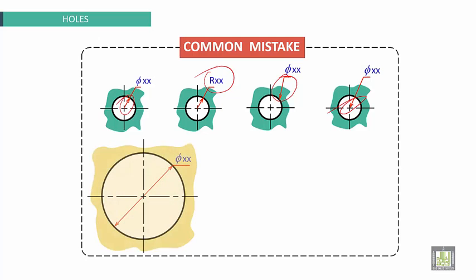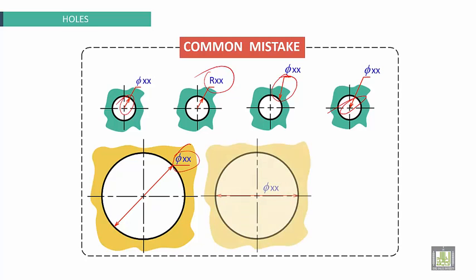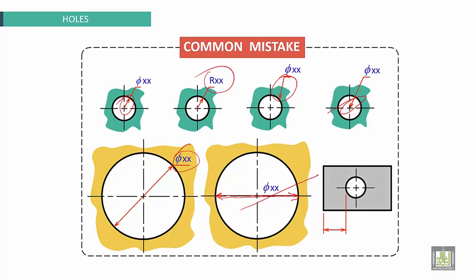This is wrong. For the big hole size, to put diametrical line, dimension, and external note, this is wrong. Also, this one is wrong. The diametrical line on the center line, this is wrong. And here also to locate the hole, this is wrong. You have to locate the center. Okay? And from here you have to locate the center.